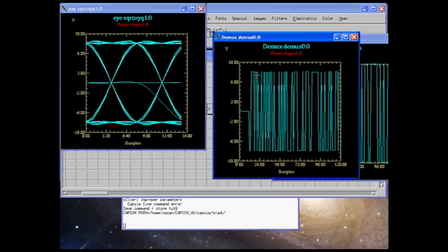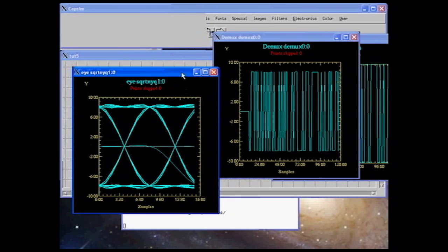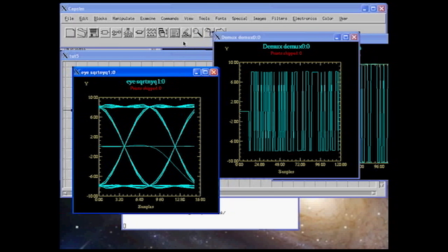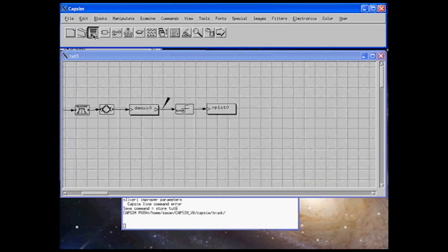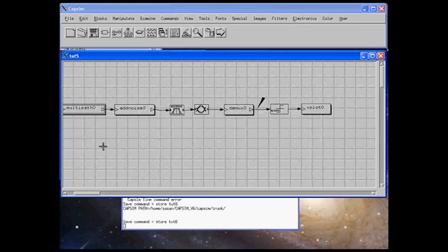As you can see, it tracks it very well. So our phase is absolutely correct, and we're sampling right at the maximum of the match filter, which is where you want to sample in the digital link. So everything checks out over here. We got a wide open eye. Let's go ahead and delete these plots, save the results, and let's go and change the noise.